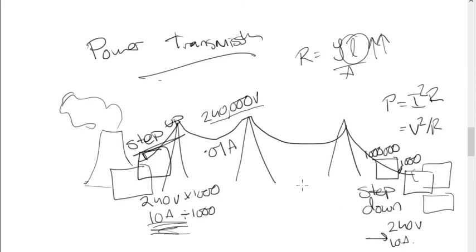So this is why we use transformers, basically to minimize line loss. ঠিক আছে? And how are we doing this? We're decreasing the current. Current decrease করলে power loss কমবে. And if you're curious, তোমার V square by R যদি এখানে use করো, again we won't be using 240,000 for V square by R. We would be using the voltage across the cable from this end to that end.